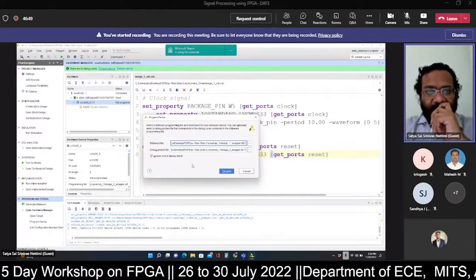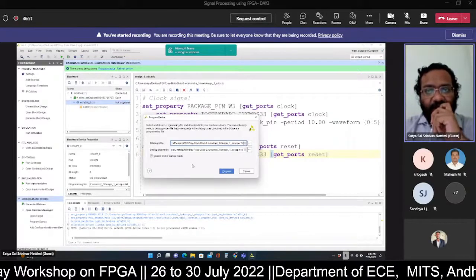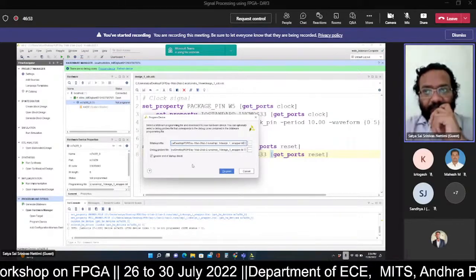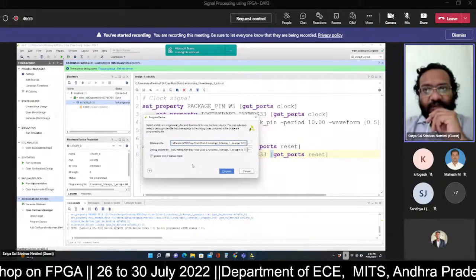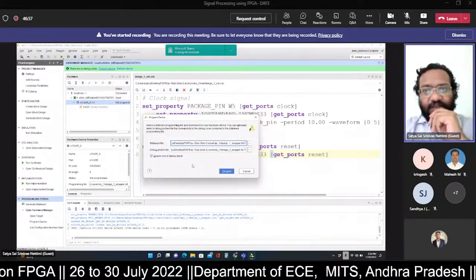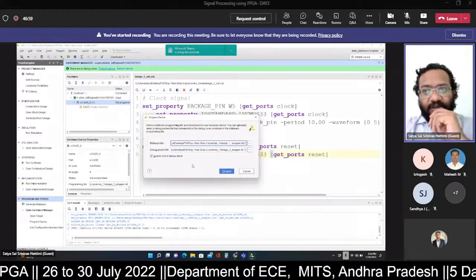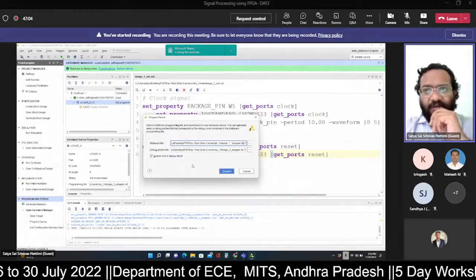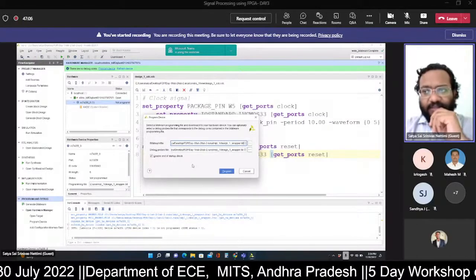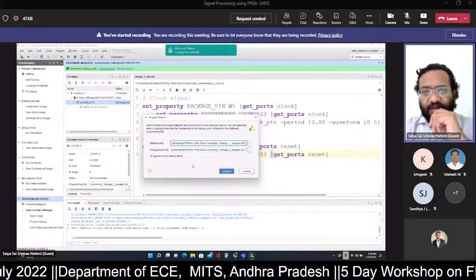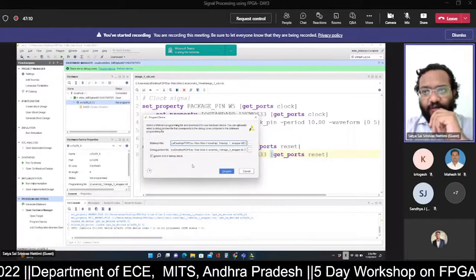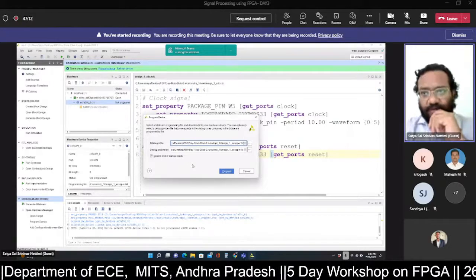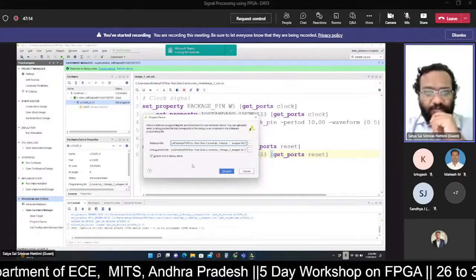As the name suggests, they are used for debugging the hardware in real time. They are very useful to check the functionality of the hardware on the FPGA, and also helpful if there are any logical errors, to identify where your circuit has gone wrong and why it is not generating the outputs properly.